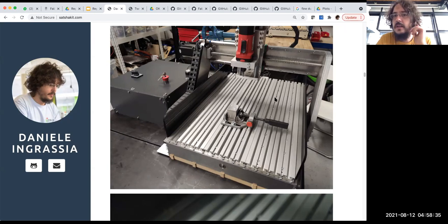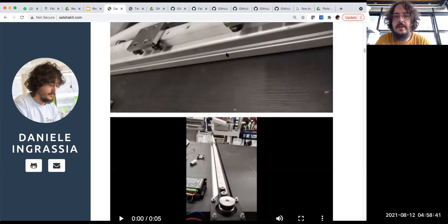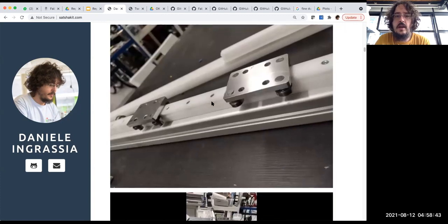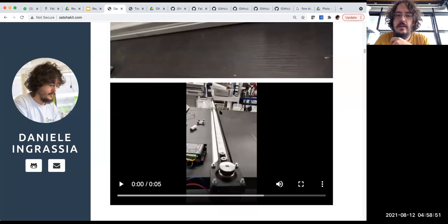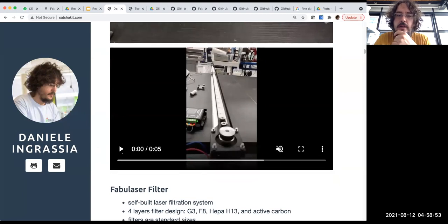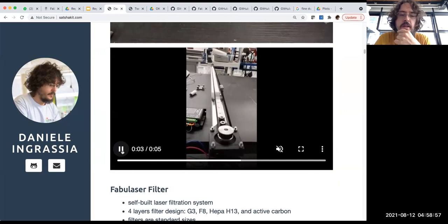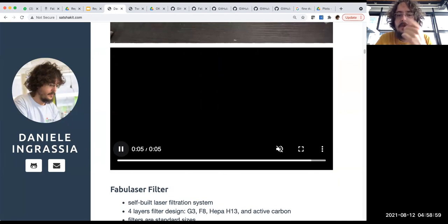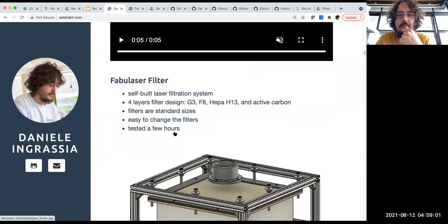I mean, all the frame is fabricated. The linear guides, I have also the self-fabricated ones. By the way, just to mention, they are here. They are very precise. This kind of linear guides I've been making in POM, CNC milled aluminum and 4 bearings, but they are not holding the force that I need yet for this. So they move very fast. Yeah, there is a video, but they are still not holding the force that I need. So they need further developments.